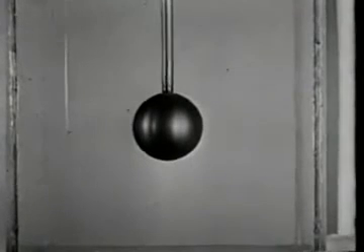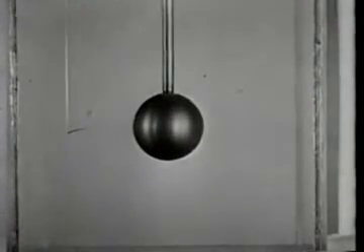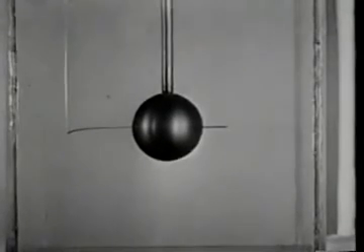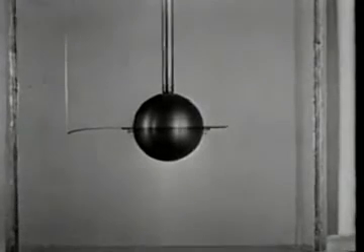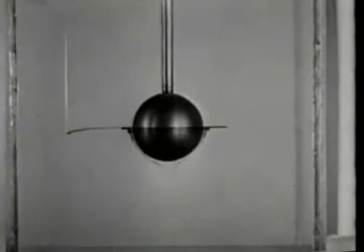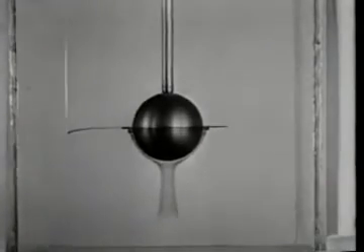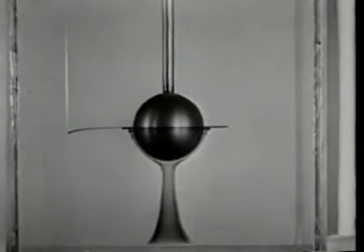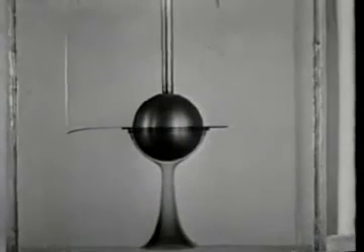Here, a sphere is rotating in a high polymer solution. Dye, introduced at the left, reveals the flow spiraling inward at the equator and outward at the pole. For a Newtonian fluid, on the other hand, where centrifugal forces are dominant, we would look for flow inward at the poles and outward at the equator.